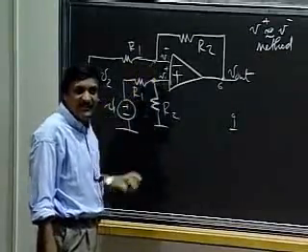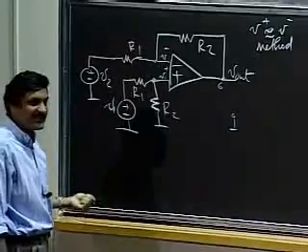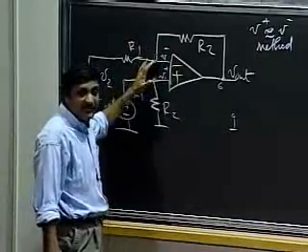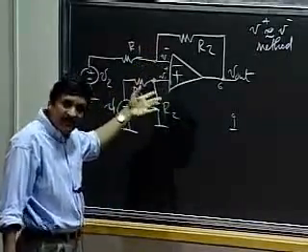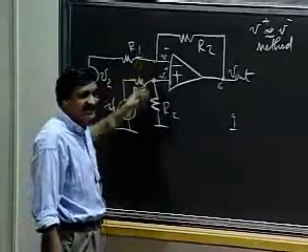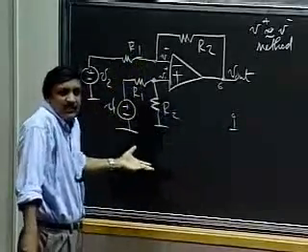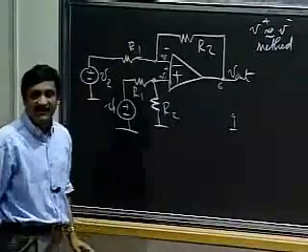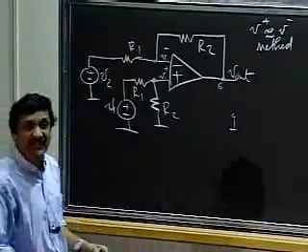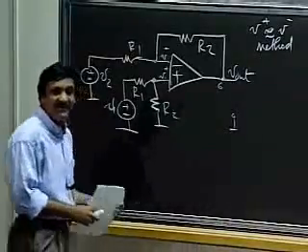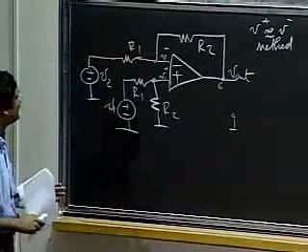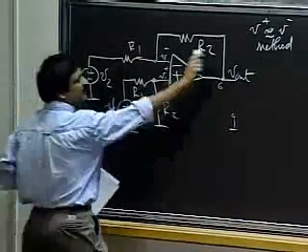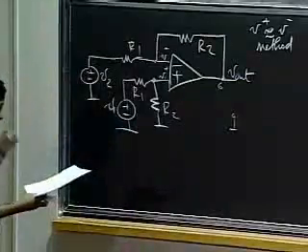This is just a bit of inverted logic that says, look, the circuit is going to make that happen. To analyze the circuit in its steady state, why don't I just go ahead and assume that to begin with? This again goes back to us wanting to be engineers here and do whatever's simple, and find the simplest possible way of getting someplace. So I'm going to use that method, the V plus equals V minus method.